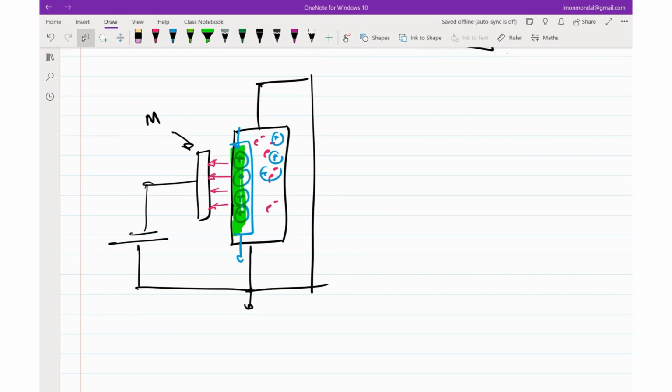Yeah, exactly. Very good question. His question is, if in place of a semiconductor we had a metal, won't it behave in the same way? The reason it will not is that you will almost never be able to get the metal devoid of mobile charges. You will be attracting positive or negative charges to the plates, but you will not be able to make the place devoid of charges.